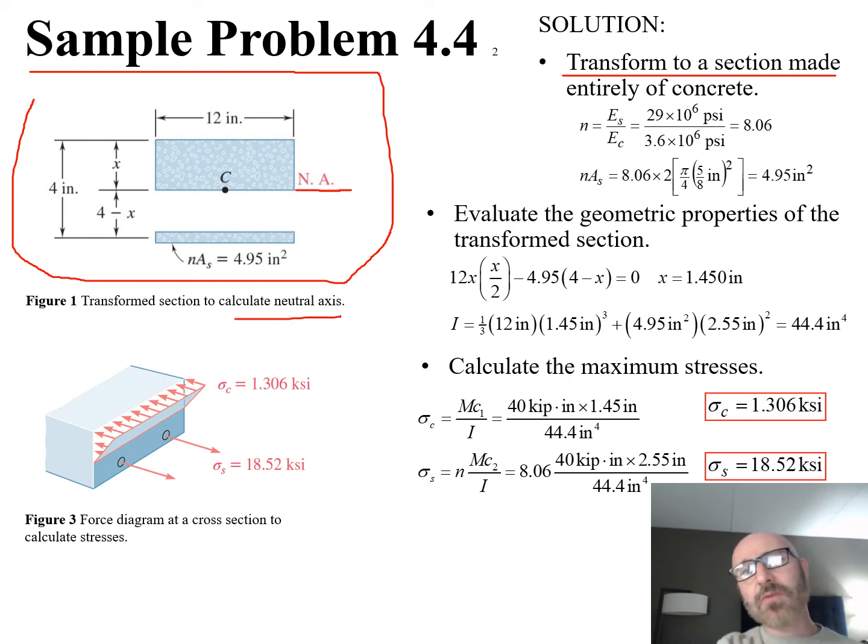The way we're going to visualize this in this figure, we're really going to have 2 of those rebar, rather than all 5 of them, for this example of how to solve this. With 2 of those, there's 6 inches on center. So if there's 6 inches on center between them, then with 2 of those on there, it's going to be a total of 12 inches of width as we look at those 2 pieces of rebar.